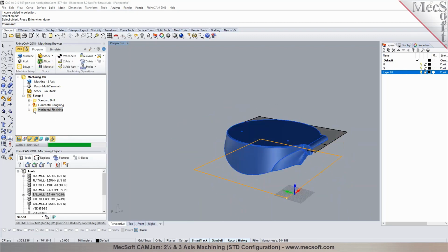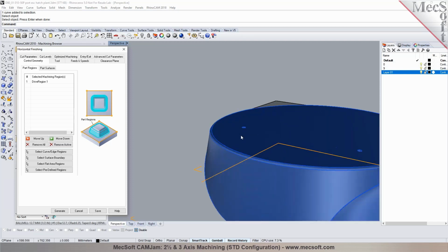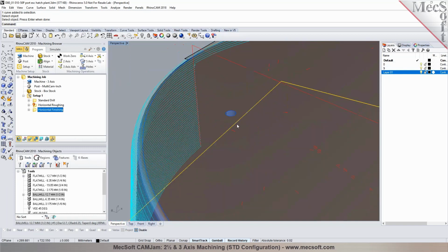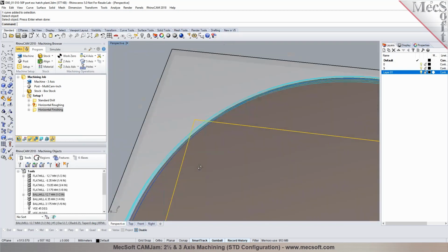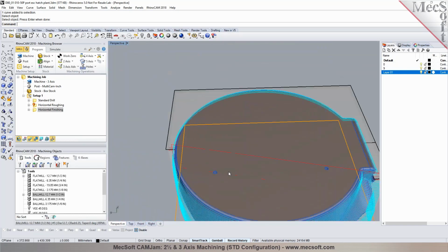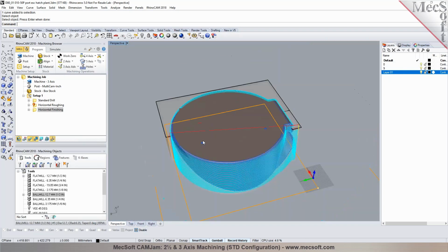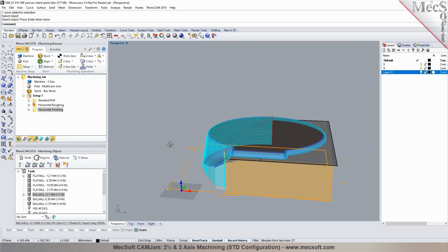So I go to the operation in here, and you have control geometry. You can click on select curve edge region, and you select it, or if it's already pre-selected. And now you'll also notice that if it is cutting into any of the holes in here, you can exclude it, but it looks like it did not get into any of the holes because the cutter was too big for those. Right. So that's a finishing in levels. You see the nice finishing toolpath.